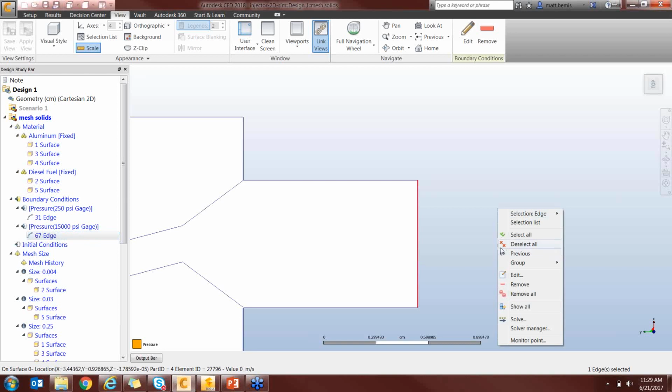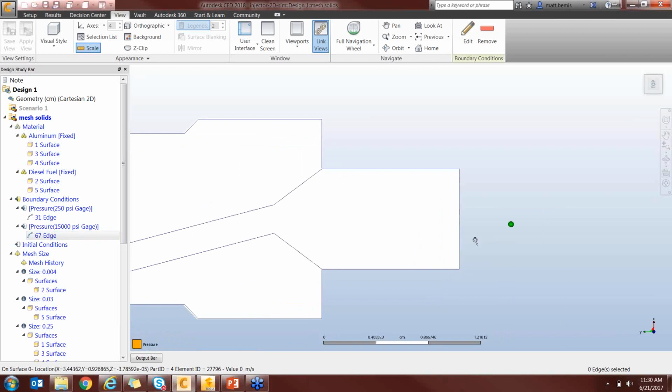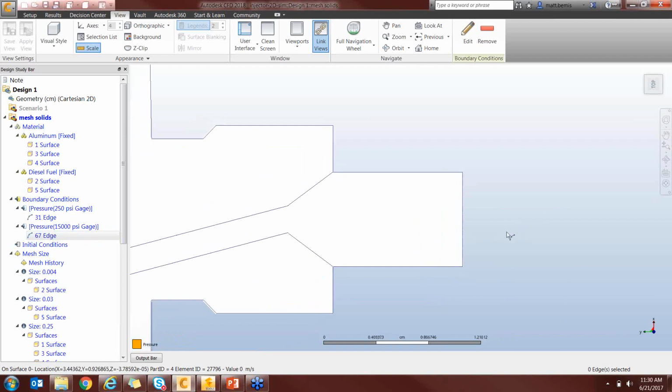Right. And that's why, if you have tons of data on what you're simulating, I would always go with either pressure or maybe velocity, because volume flow rate is just going to make you think a little harder. But in 2D or 3D, pressure's pressure, in the flow direction or across the flow direction, it's all the same. And velocities are easy enough. You just have to make sure you're prescribing the correct velocity.